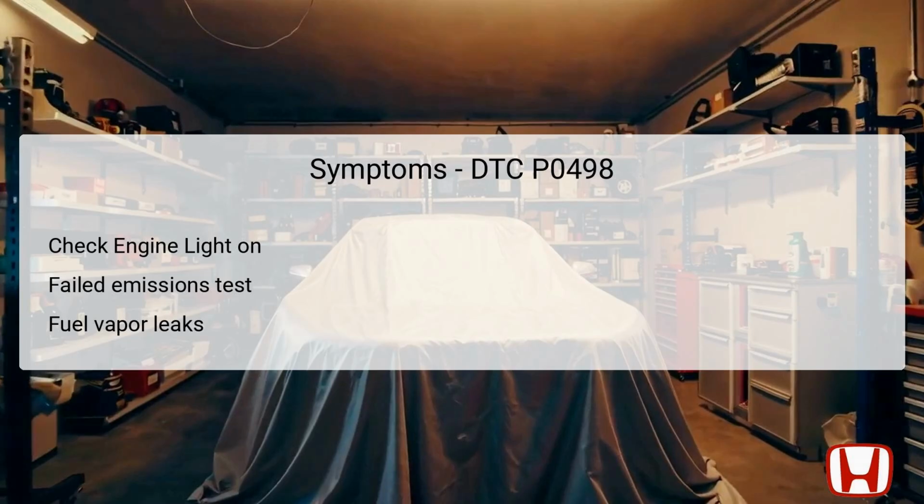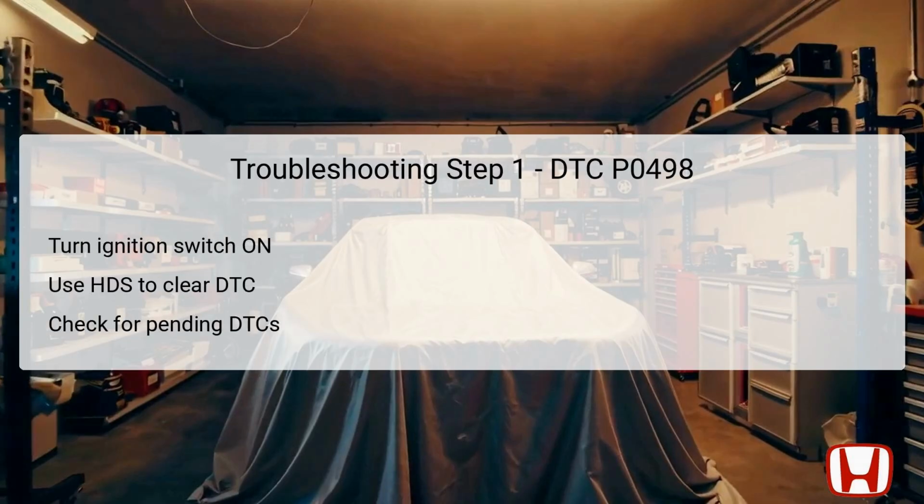The first troubleshooting step for DTC P0498 involves turning the ignition switch to on-2, which powers the vehicle's electrical systems without starting the engine. Following that, use the Honda Diagnostic System, HDS, to clear any existing diagnostic trouble codes. This action serves to reset the vehicle's computer and allow for new data to be recorded without any historical codes interfering.